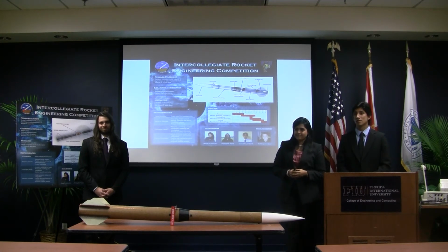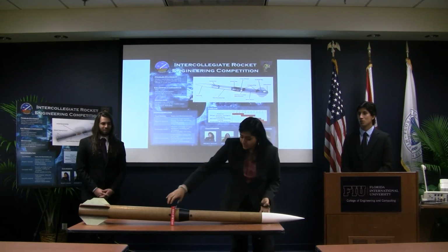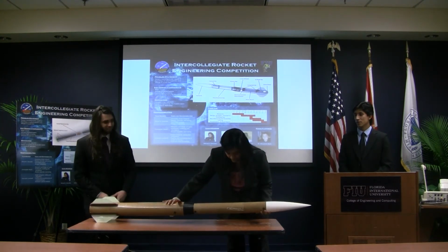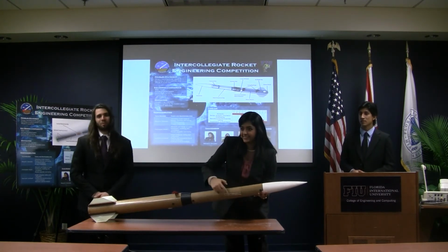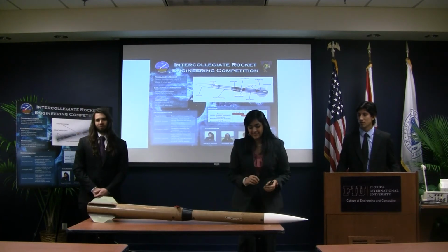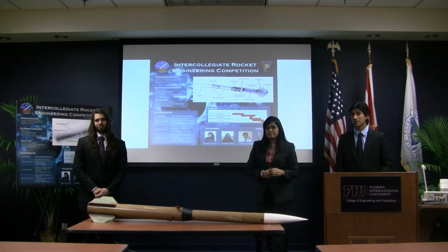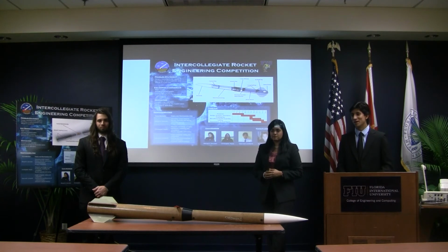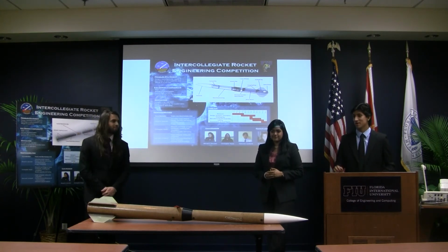Is that going to fly again? Yes, it can fly again. All we need to do is fix this portion of our rocket. There's a tear on the fiberglass layer of the airframe. We have extra composite that we're planning on just patching it up and trying to keep it as smooth as possible, but it'll fly again.